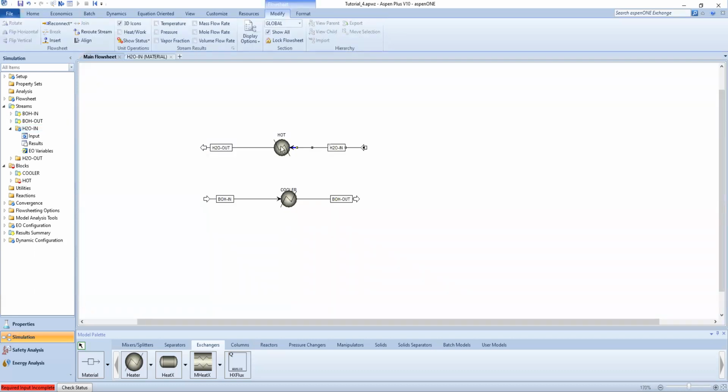So now I need to specify the 2 degrees of freedom required for the heater model. And we said the first one will be pressure drop is 0, and the second one will be the heat being transferred from the cool stream. So while we're on this page, let's draw the heat one. So my mouse now is at the bottom left here on material. I'm gonna click on the small arrow next to material. I'm gonna select the heat, not the work. Heat exchangers don't do work, right?